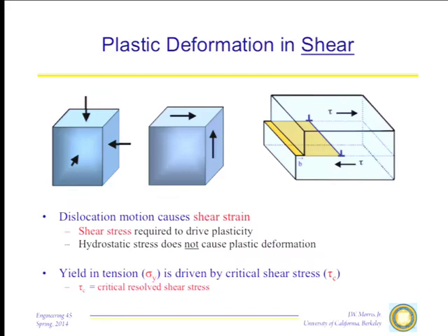It is the shear stress, and there would really be three different shear stresses since I can use any set of two planes here. It's the shear stresses that are changing the shape of the material. And it's also the shear stresses, as we discussed earlier, that drive the dislocations, that cause dislocation plasticity. Remember when we first discussed dislocations, here's an edge dislocation in a simple material, which you would make by making a cut in the material, slipping the top of the material over the bottom of the material by the Burgers vector b, and then sealing it back up again.